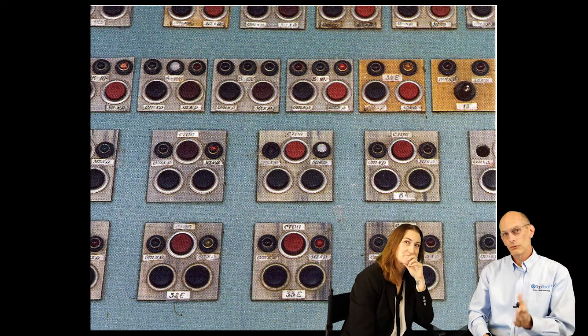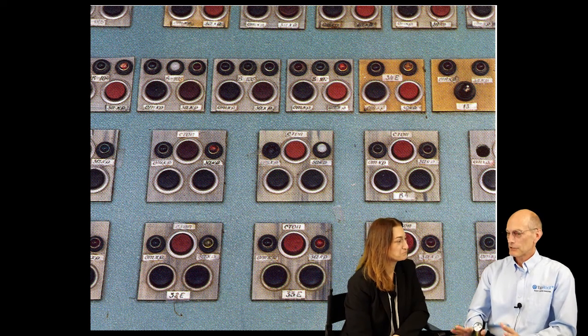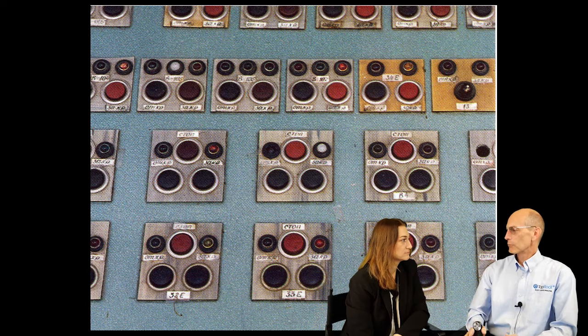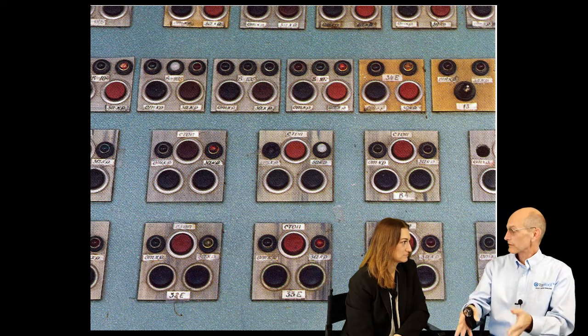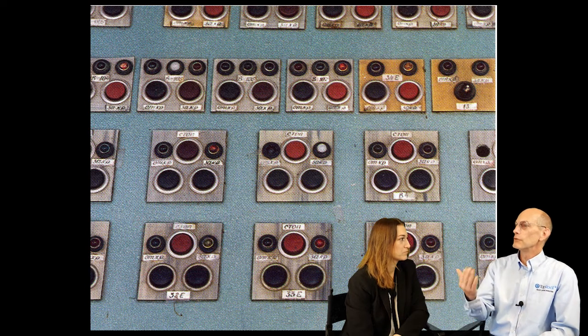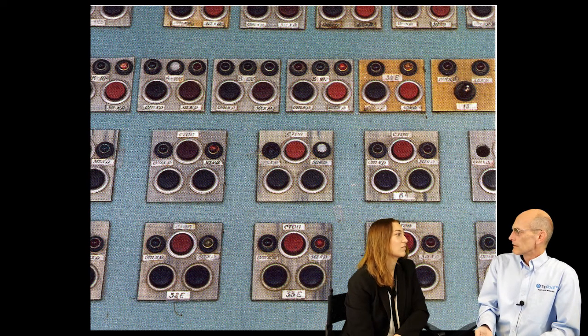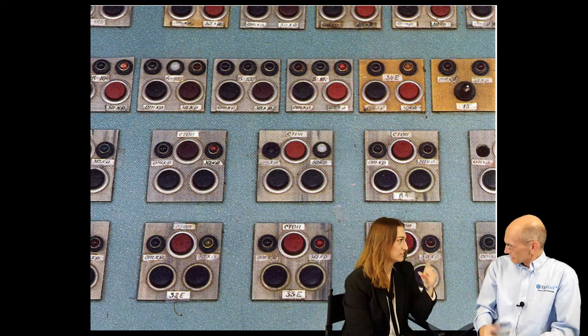And then you go down and you look at the control panel and you say, well, how did this guy overpressurize the tank? Whenever you have a human engineering issue, it's very important for the investigator to actually go down and look at what the operator is physically doing. This isn't one where you can just interview the guy and say, tell me what you did. Right, because he's going to tell you why he was pushing buttons. You want to physically see what he saw. You've got to see what he saw.